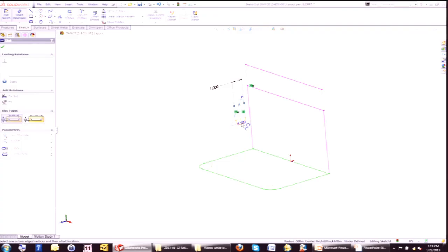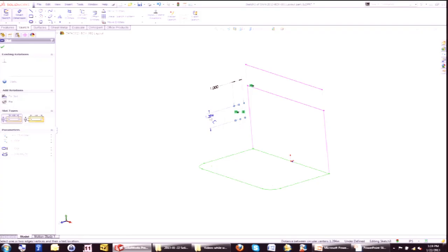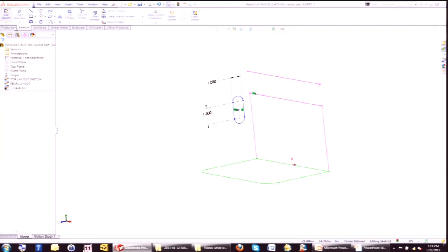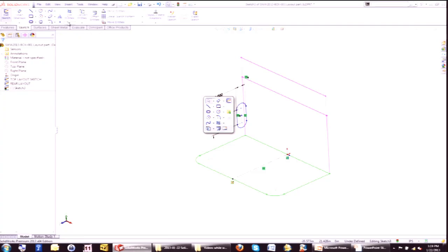All right, so I'm going to create this guy here. This is going to be 1.5 inches. And then as far as aligning it, I could put in a dimension from the back of the box, or I could create some more dynamic setup, like a mid-plane type of a thing. So I could maybe create a line that comes across here and then pierce this. So select one, hold control, select the other, let go of control. And then I could right-click, select midpoint.